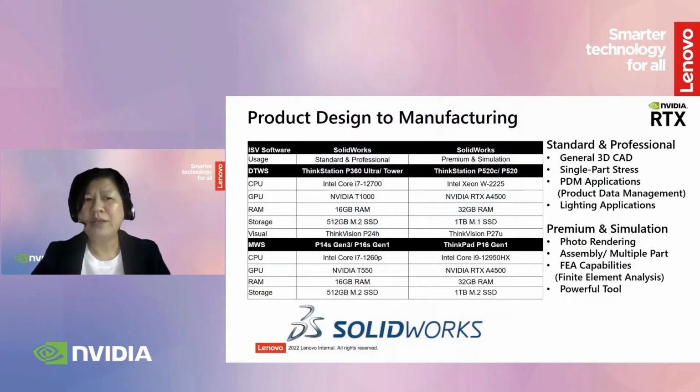If you're just running SolidWorks Standard or Professional, P360 Ultra or Tower will do the job. Or you can go for P14S Gen 3, or P16S Gen 1. But if you need to run Premium and simulation, then at least a P520C and P520, or a P16 Gen 1. So this will help you to choose for your SolidWorks application. That means if your workstation is only running SolidWorks, then this will be the recommended spec for you.